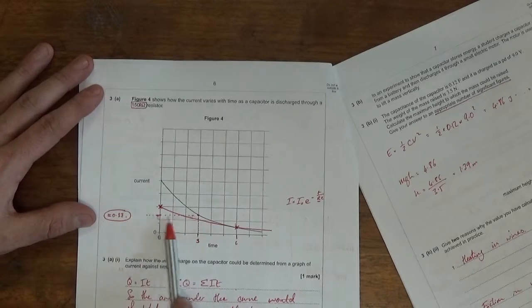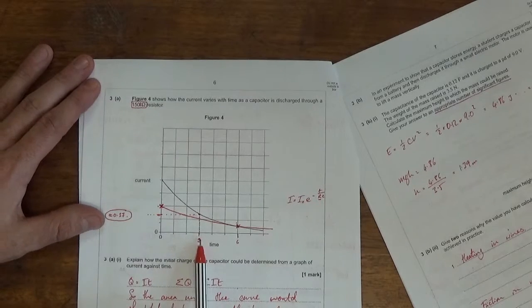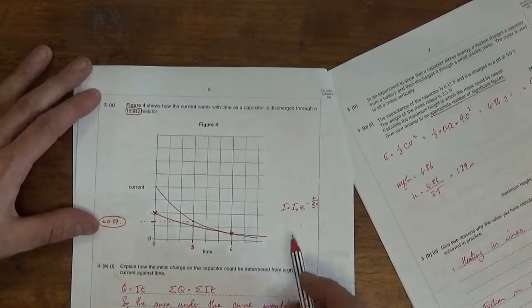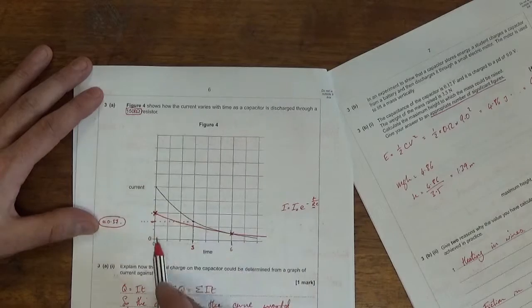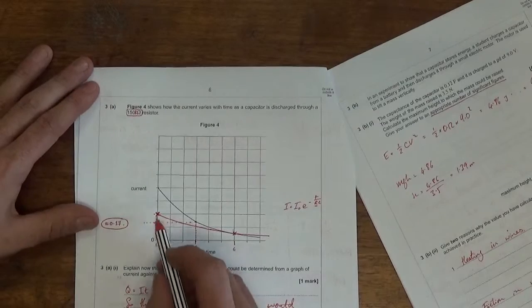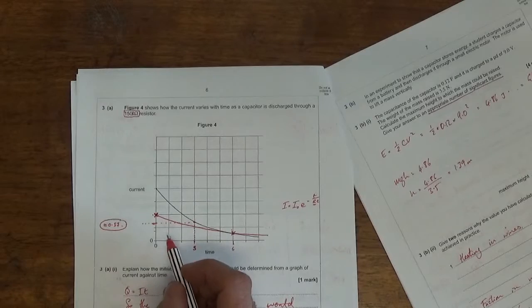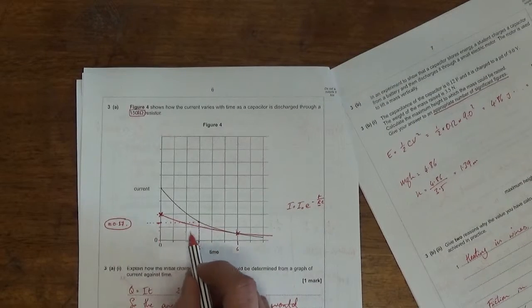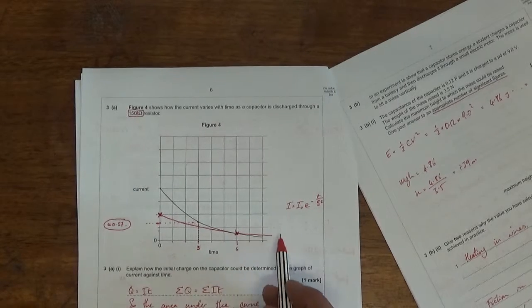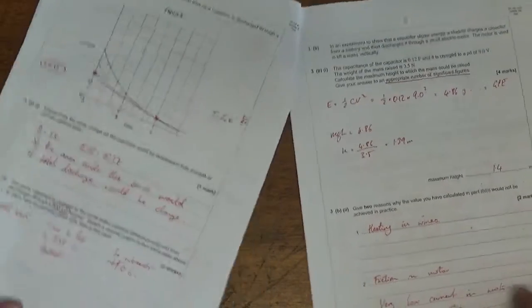So here, the initial time constant is 3 units of time. We don't know what they are, seconds, let's just say. And of course, if we've doubled the resistance, then we should double the time constant. So there's my first point, and it's going to take 6 seconds to get to 0.37 of this amount. I keep wanting to say percent for some reason. But anyway, I'm just going along there and saying, well, that's roughly there. So you get this graph doing that. And that's worth bearing in mind because it's good knowledge to have. All right.